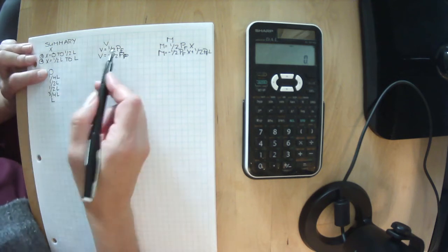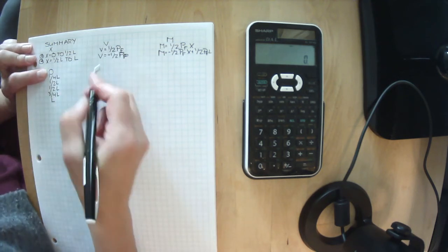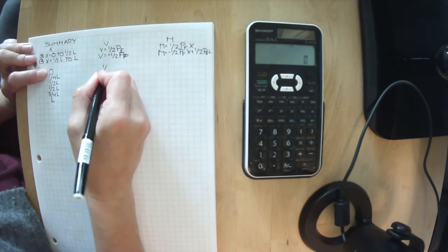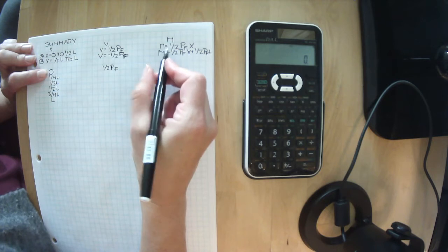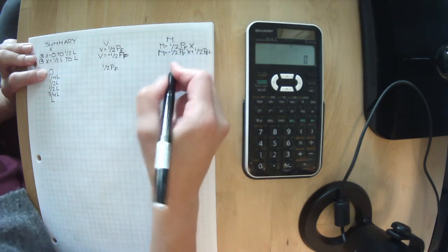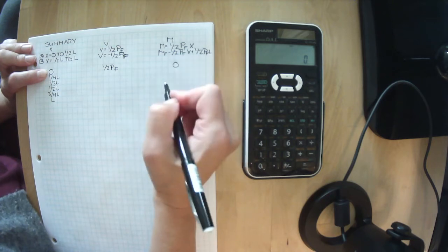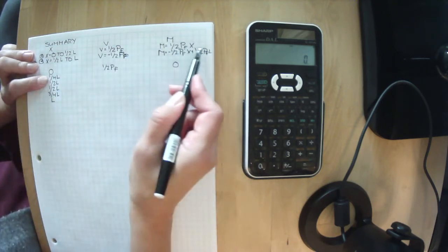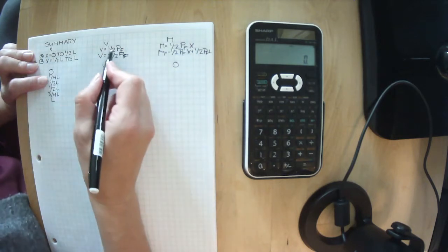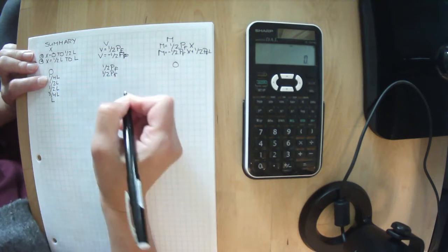So when x equals 0, we get to use this equation, which is 1/2 PF. So shear equals 1/2 PF. M, if x is 0, is 0, because x would be here and knock everything out. At 1/4 L, we're using these equations. So 1/4 L, it doesn't matter. We're 1/2 PF, doesn't change the value.